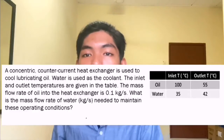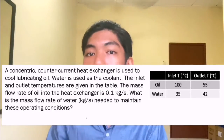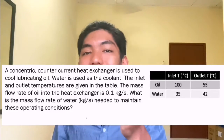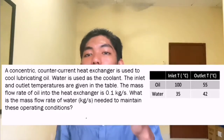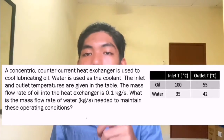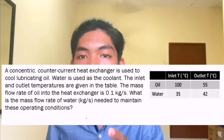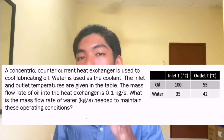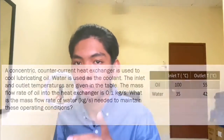Now, let's do some problem and solution. Okay, what we get here? A concentric counter-current heat exchanger is used to cool lubricating oil. Water is used as the coolant. The inlet and outlet temperatures are given in the table. The mass flow rate of oil into the heat exchanger is 0.1. What is the mass flow rate of water needed to maintain these operating conditions? Okay, let's see the solution.